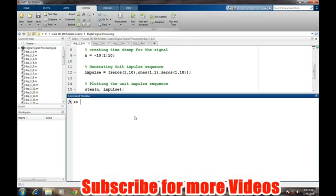Before generating any signal, we first need to define the time stamp over which we will define the signal. We are taking the time stamp from minus t to plus t at a difference of 1. Because it is a digital system, everything is in sampled form. We will take the samples from minus 10 to plus 10. After that we will generate the signal.